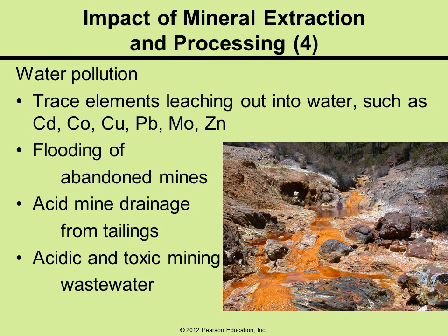One of the areas where mining has the opportunity to get off-site is through water pollution. Trace elements leach out of the water that circulates through a mine or through mine waste, and we could have accumulation of cadmium, cobalt, copper, lead, molybdenum, and zinc accumulating in the waters that are transported off-site. Here you have an image on the right showing a depiction of such a transport. You could have problems associated with the flooding of abandoned mines in a wet area. If you create a void at the surface or at depth, it's very likely to accumulate water that can act to leach out these trace elements.